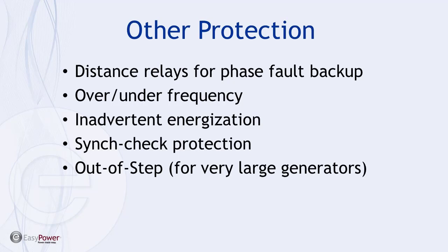Over/under frequency, again, this is going to be tied to your volts per hertz, but also your interconnection requirements. Obviously there's going to be limitations on the frequency range that this system can operate at, but normally your grid requirements are going to be more severe than the actual machine limitations.